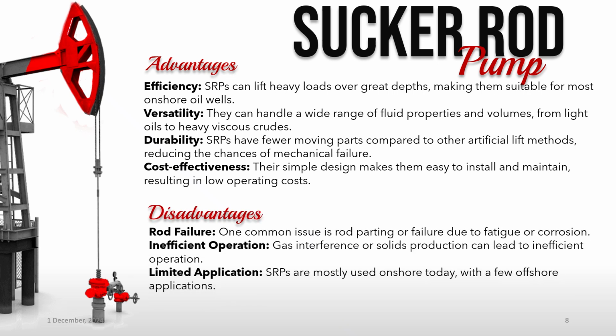One of the most common operational issues encountered with sucker rod pumps is rod parting or failure. This can occur due to fatigue from continuous cyclic loading or corrosion, especially in wells producing corrosive fluids. Regular inspection and material selection are crucial to mitigate this.